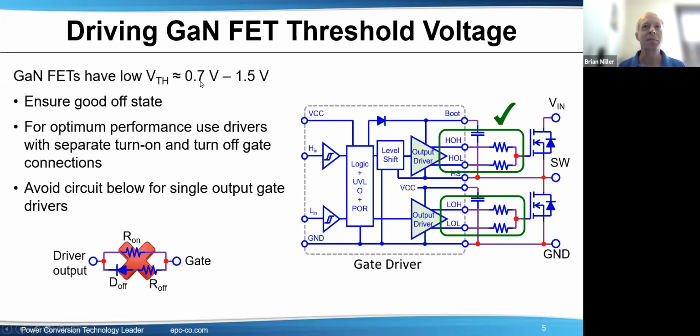If you have 0.7 volts minus about 0.4, you're at 0.3, and a little bit of noise could cause slight conduction. You really want to avoid that. So just a very simple circuit with just resistors works the best. That's what's in evaluation boards and almost all successful designs.